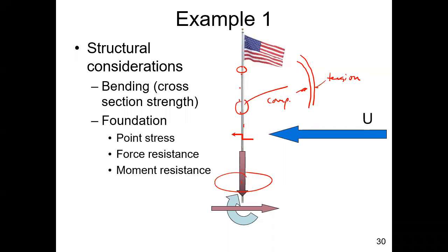Well, the first thing is you find your design condition. What is the loading and what is the geometry of your structure? And then you can define the drag forces and the stresses, the driving forces, the driving stresses. And with that, you then design each component. So for example, if this is your flagpole and you say, well, I'm going to put it in a hole that's just 2 feet deep, and I'm going to make the hole 1 foot in diameter and just put the flagpole in concrete. But if the soil can't generate that amount of resistance, then the flagpole just tilts over.